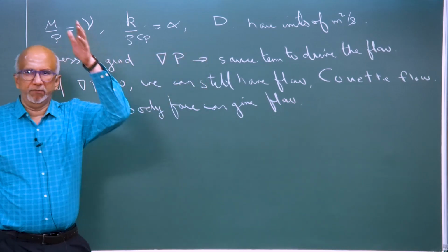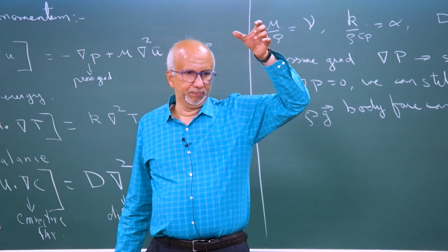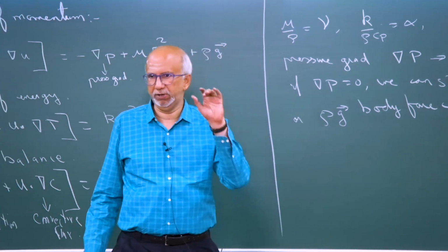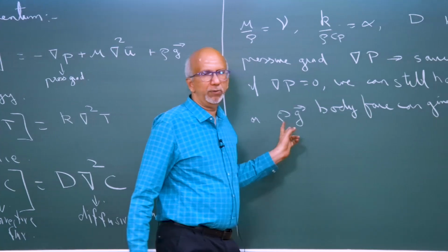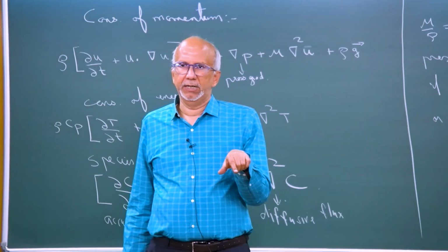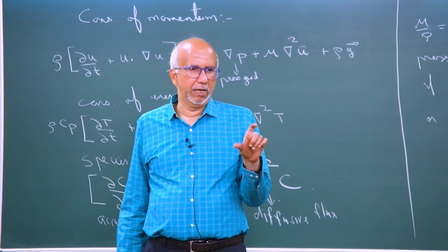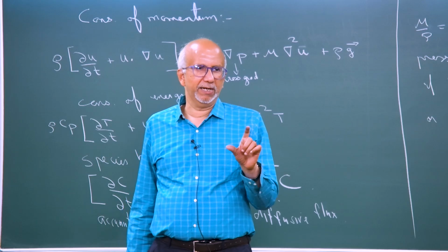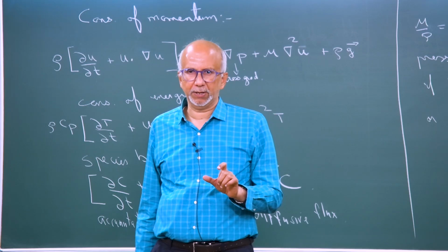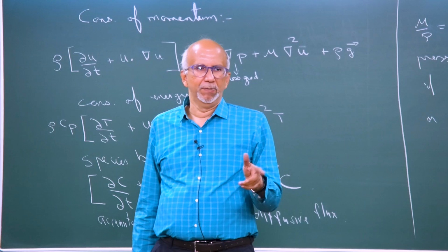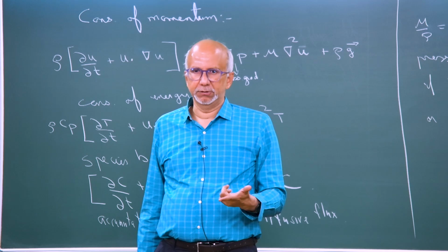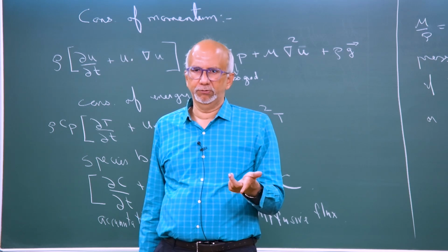We saw that problem where we had that vertical wall in which the gravity was dragging the fluid down, okay. If you remember, long time back we spoke about that problem. Now, in addition to these body forces, there could be other forces also depending upon the nature of the fluid. For example, if your liquid contains ions or a ferrofluid contains magnetic nanoparticles, okay, then if you were to apply an electric field or a magnetic field, that will also induce forces, okay, and that can give rise to fluid flow.